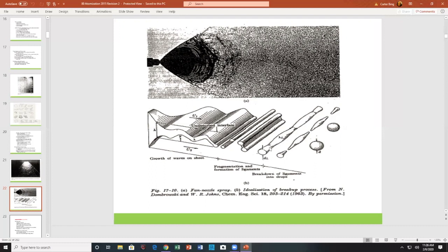The curvature, the radius here is small. That means this area right in here is high pressure. The radius is small, so surface tension means you have high pressure there. This is a larger radius, again surface tension, lower pressure. So what happens, high pressure fluid, which sits here, moves to low pressure regions, which stay here. So this is a thin spot, but it's drained even further due to surface tension.